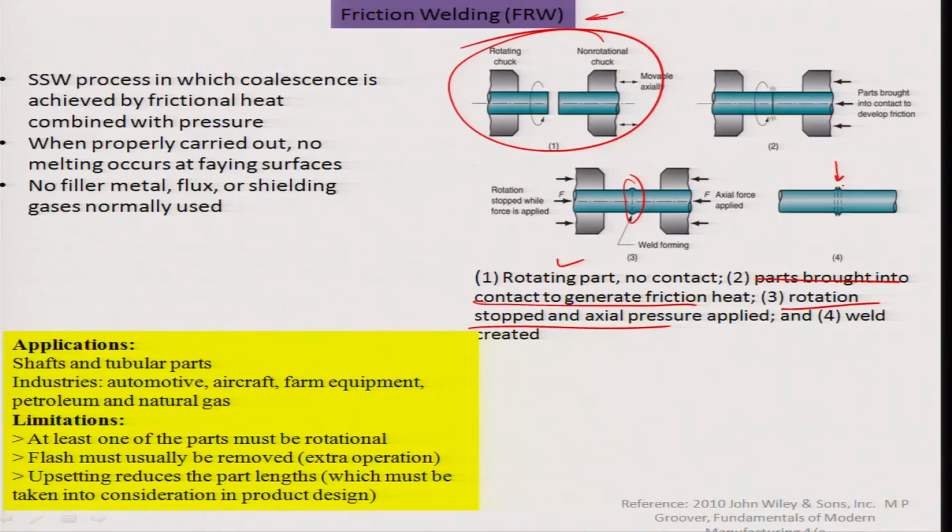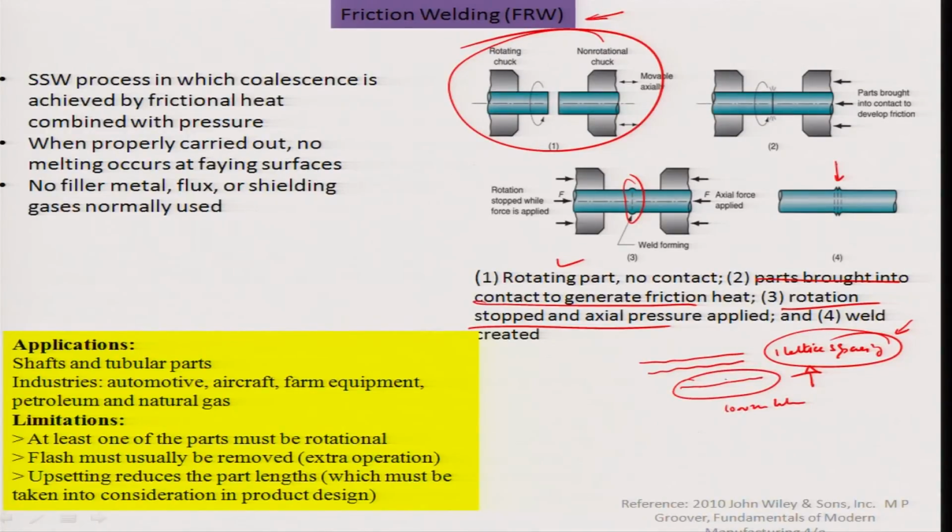So this is also a sort of solid state welding, and here I would like to illustrate one point. Please remember, in one of the modules earlier I had mentioned that when you bring two layers atomically close to each other, so that the gap between the layers is of the order of only maybe one lattice spacing, the ultimate yield strength in this kind of orientation is much higher than the case where a crack has propagated and there are several lattice spacings, maybe let us say 10 or more, involved.